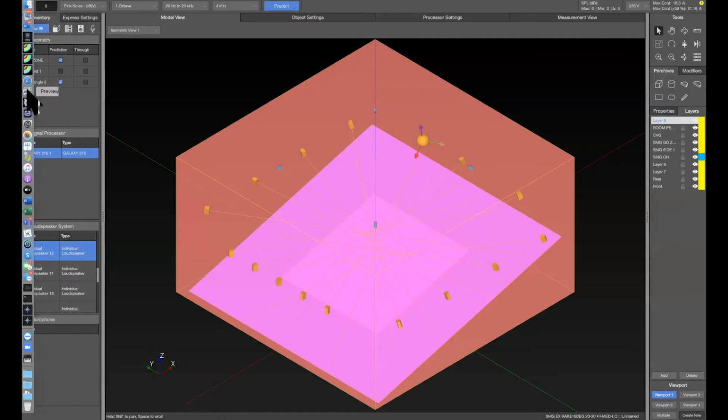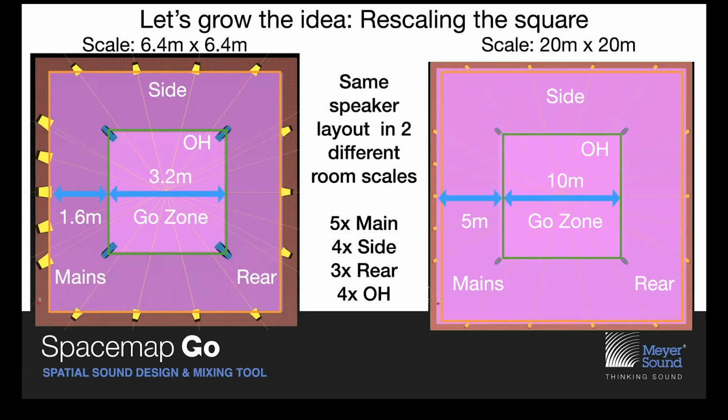I'm going to take one very brief minute to review what we covered in the previous 2 weeks. I can't do it all, of course. That would be a big waste of everybody's time. But the key concepts that we go to is that we have a go zone that we create as a portion of the space. It's basically, we use this G factor, the go factor, which is 1/4 of the shortest side. And we design around that to get the proper spacing between speakers and the proper aim of speakers.